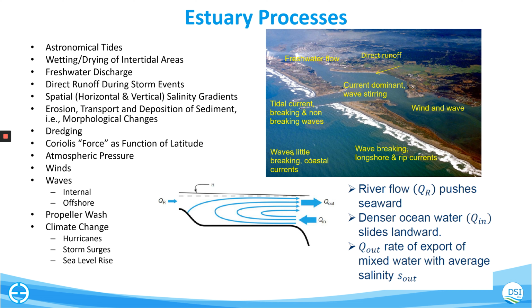So one feature of estuaries that can be kind of challenging from a modeling perspective is handling of wetting and drying. As I showed you yesterday in the hydrodynamic settings, we have a good amount of control over how much time EFDC is going to wait before it will check if a cell is wet or dry again.